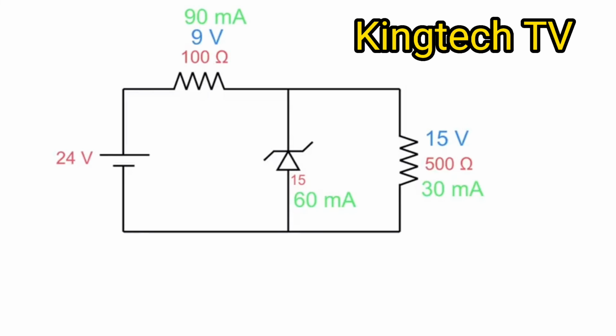And that's it. That's as far as you need to know really for a Zener diode circuit acting as a voltage regulator. As long as you remember that this Zener has to be in reverse bias. If it was the other way, then you would just see the regular 0.7 volt drop across it. So as long as you have this fella right here in reverse bias to the source, you're good to go.